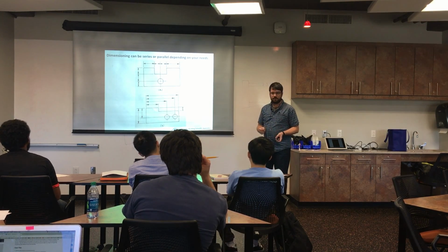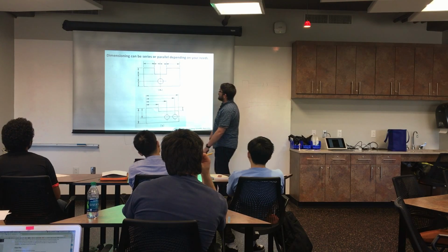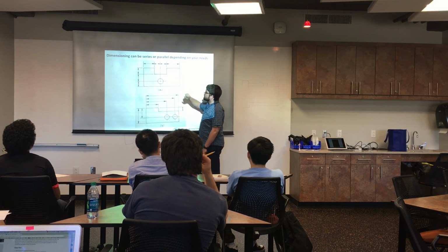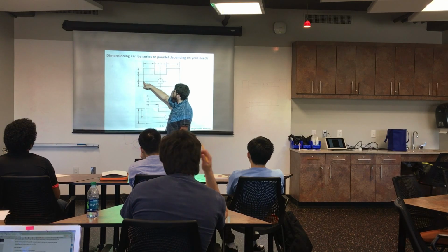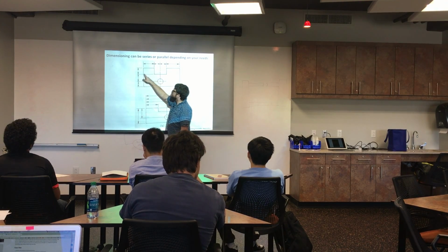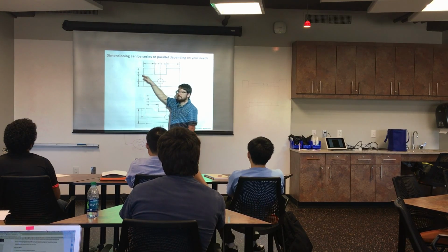Depends on what's important to you. So the top part is dimensioned in series. We specify the dimension to the center of this hole, and we specify the dimension to the bottom of this, and then we specify the dimension to there. And they're all chained together.